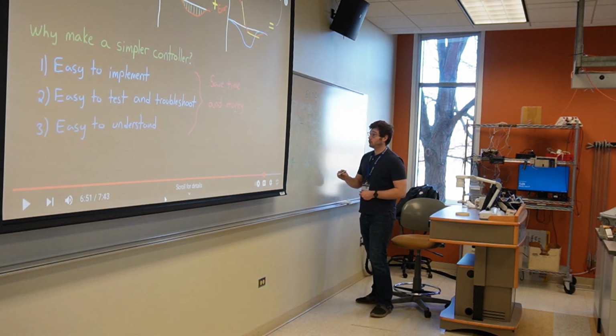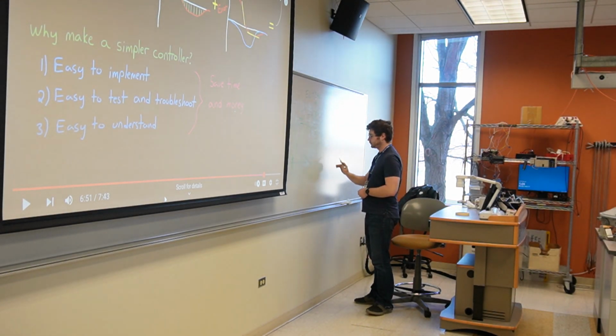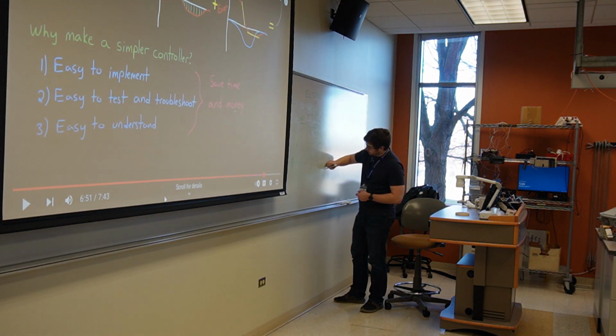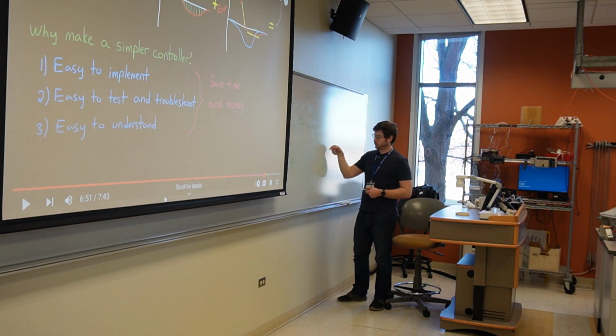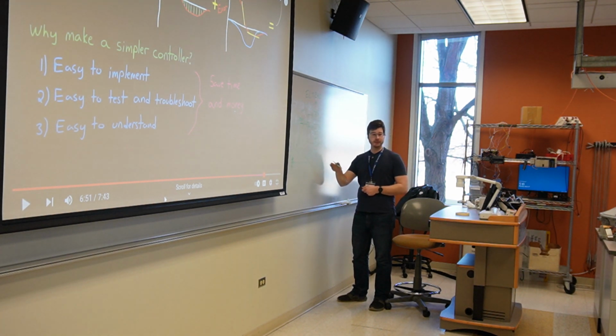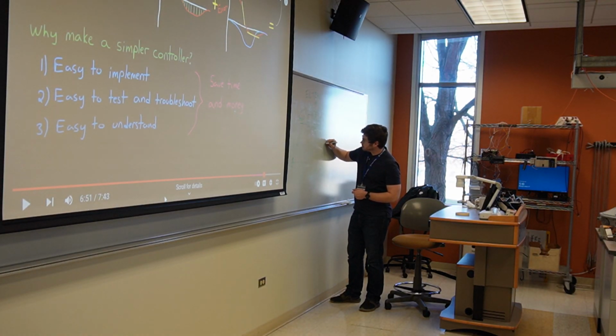The downside of the proportional controller is that it can't correct over the long term. Imagine our tilt situation again. We have a tilting device right here. We can figure out what this angle, theta, is, but we want it to be perfectly upright, at a 90-degree angle. If we use a proportional controller, and gravity or some force was pushing it this way while our proportional controller was correcting it back this way, it could come extremely close.